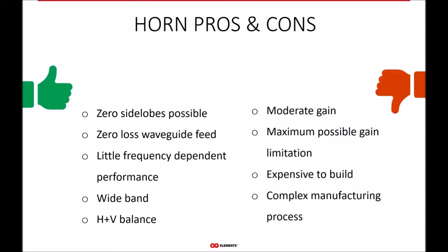So here's a short summary of the properties of horns. The present state of the industry is that for the vast majority of WISPs, RF noise or interference, be it self-interference or from competitors, is the biggest issue. This is where horns actually bring a good proposition. The zero side lobe radiation pattern will definitely help with this issue.